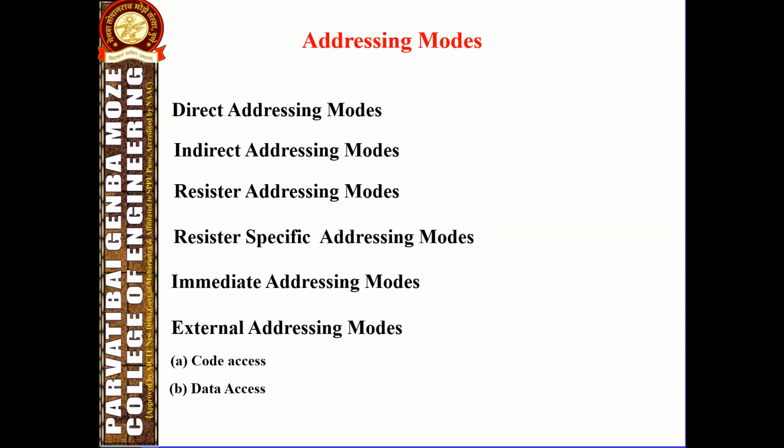One can access all 128 bytes of internal RAM and the special function registers directly using the single byte address that is assigned to each RAM location and each special function register. So the entire 128 bytes of RAM, from 00H to 7FH, can be accessed using direct addressing mode.